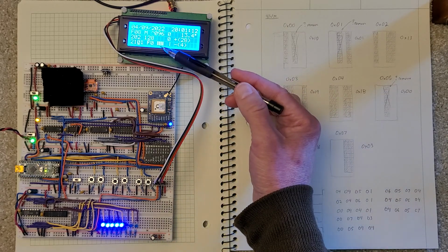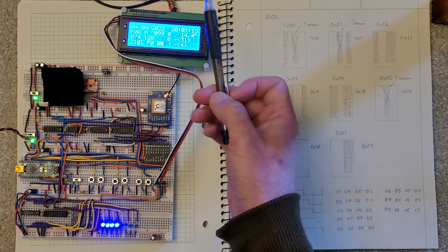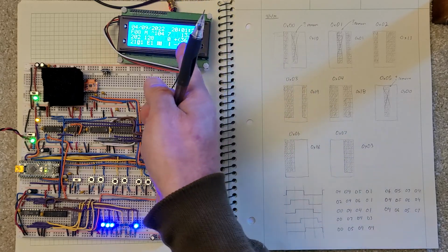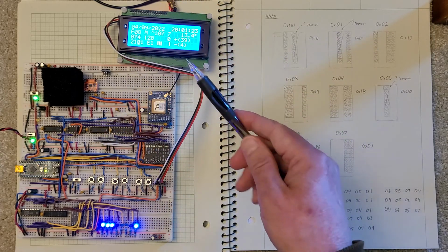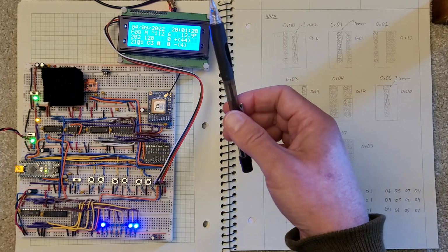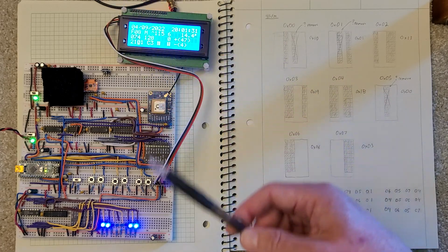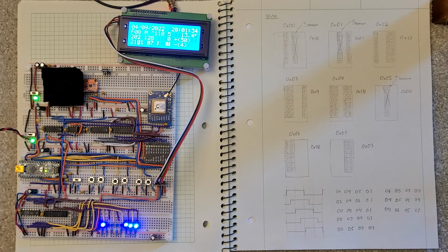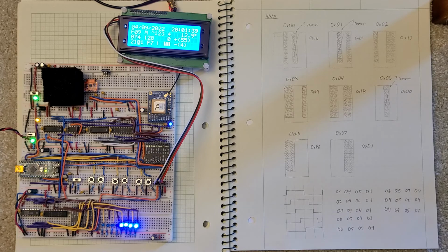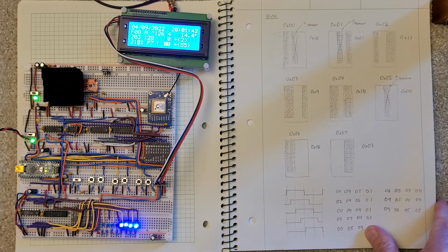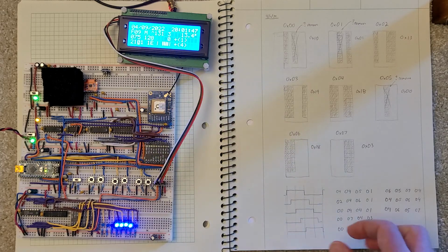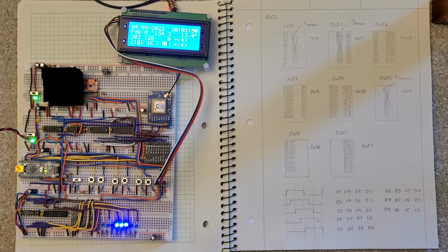A human would want to look at this, and so when the edges are walking that way, it's going too slow. You need to speed things up. When the edge is walking that way, you need to slow it down, because again, this is time. So if these edges are creeping forward, that means more of them are occurring earlier and earlier because they're actually coming faster. And by the way, I'm happy with it going almost a minute and just sitting here without slipping an edge. But of course now I'm in danger of doing the jog, which it just did, or the jitter. So that all works out well.